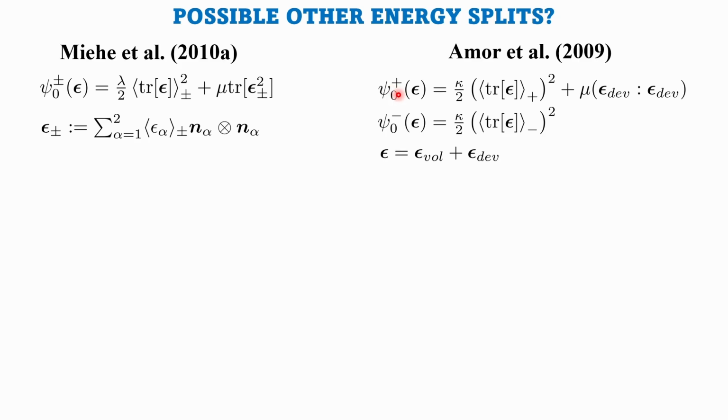Okay, so the phase field variable inside the g of phi is always multiplied to psi 0 plus. And psi 0 plus contains the deviatoric part of the strain tensor. Okay, hydrostatic is volumetric. So epsilon vol is the hydrostatic, or volumetric, part, and dev is the deviatoric part.